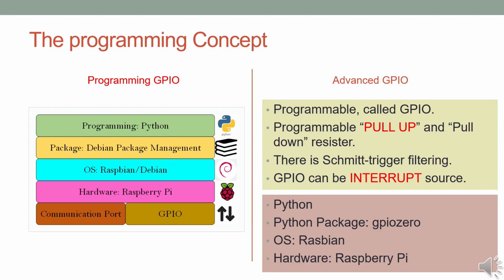Python controls GPIO through libraries, RPi.GPIO or gpiozero, rather than directly. gpiozero simplifies GPIO usage by abstracting hardware details, providing intuitive object-oriented interfaces, like Button, LED, automatically handling internal circuits like pull-up resistors, supporting interrupts and callbacks with simple syntax. This approach allows developers to focus more on functionality and logic and less on low-level hardware setup. By leveraging gpiozero, GPIO pins on the Raspberry Pi become much easier to use, even for beginners, while still allowing access to powerful hardware features.